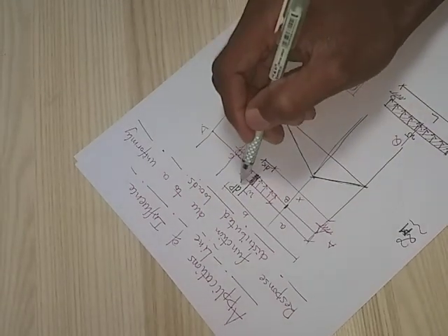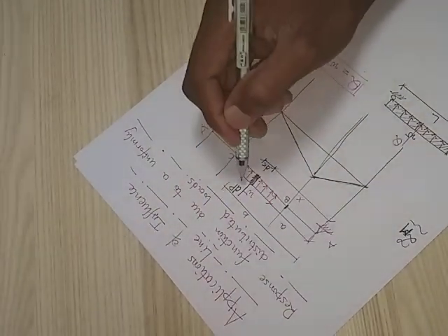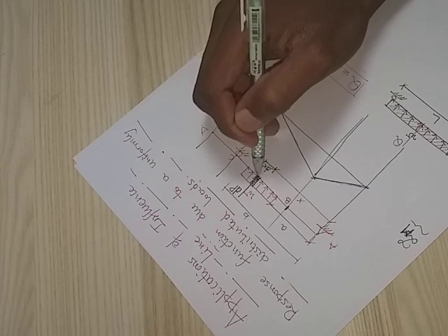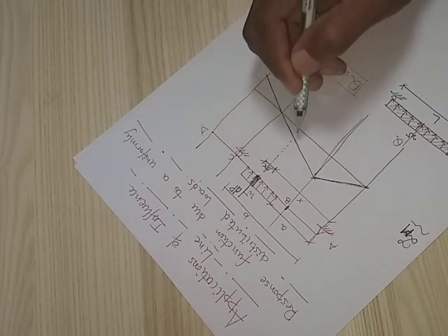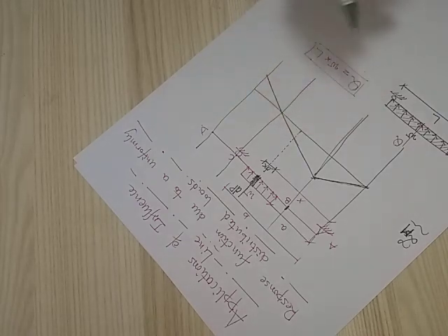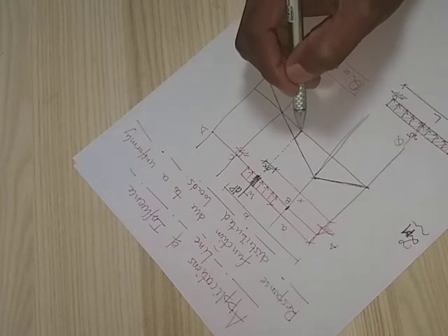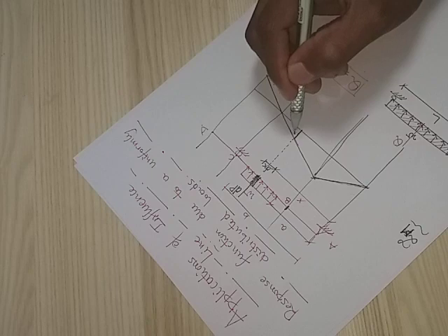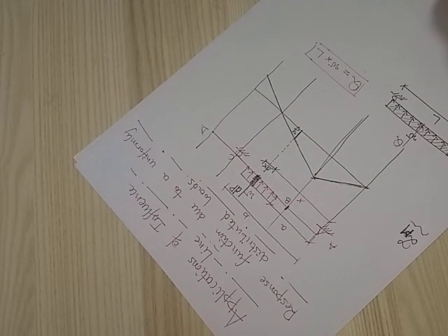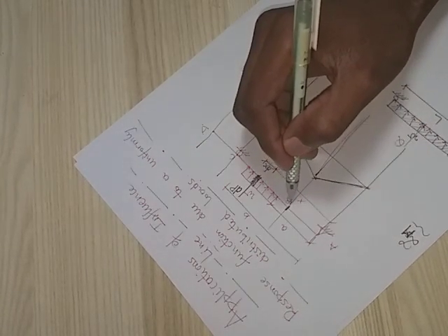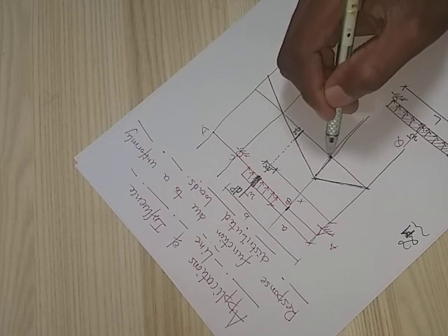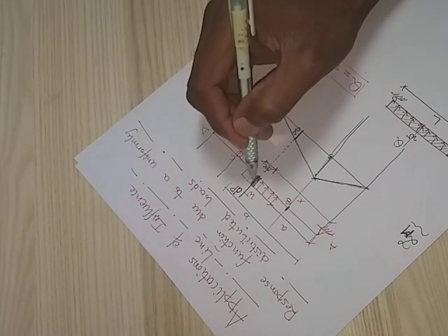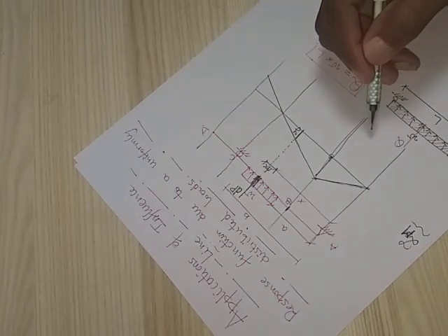We call it dP. At the point of application of that load, we can find the corresponding ordinate under the influence line diagram. We call it y. At the section B, we want to find the moment created due to this differential element.